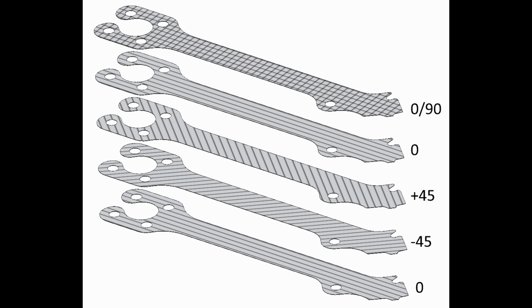The second layer is this zero orientation intermediate modulus fiber. Next after that is this plus minus 45 direction, that is actually T700 in our case. Those are there to handle the twist. Torsional. Yeah, exactly. And then we're back to 0. So we don't have the 90 degree layers that you would normally have pretty high up.